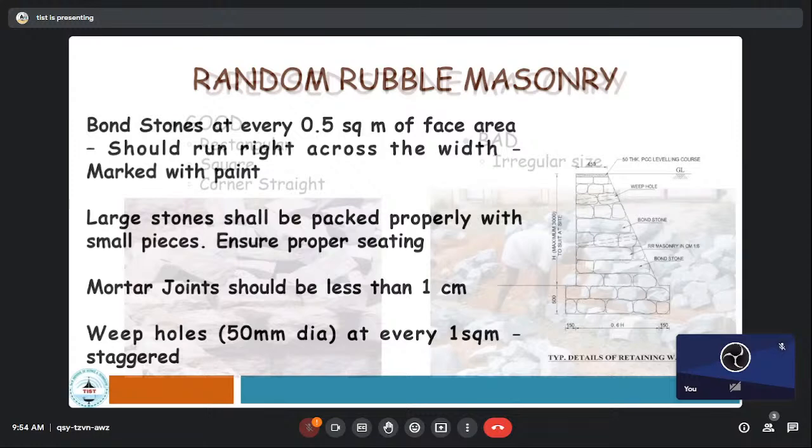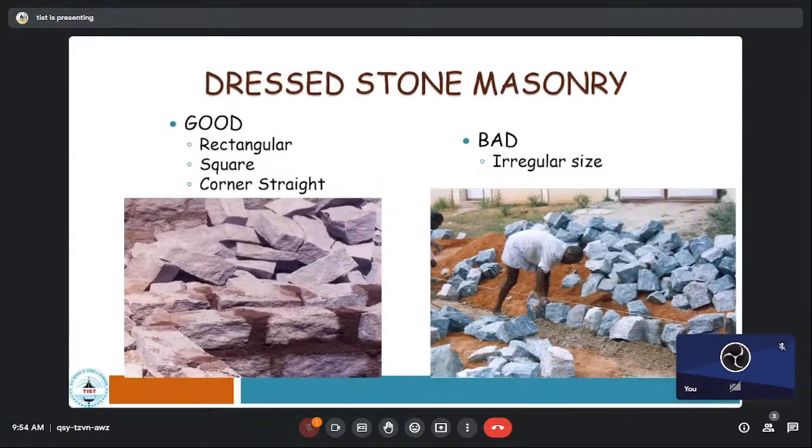Now you can see, normally the stone masonry is the place where all sorts of mischief will happen. They will not be regularly packed, dressed properly. Thus, all the stones that we are getting, RR that we are getting, have to be dressed, knocked. Why is that knocking so important, you know? All the stones or the boulders that we get to the site will not be perfect always. You know how it is being extracted from a quarry?